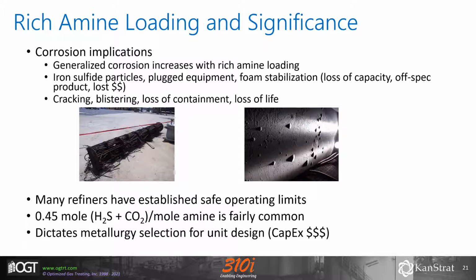So, getting further into rich amine loading and its significance, there are some fairly serious corrosion implications with acid gas in solution. The richer the solution is, the higher the generalized corrosion is. In the simplest terms, the particles you form, which are the corrosion product, plug equipment, stabilize foam, and lead to lost profits. But what we really want to avoid is the cracking and blistering. Those events are catastrophic failures of the equipment that are hard to predict and lead to big time problems.